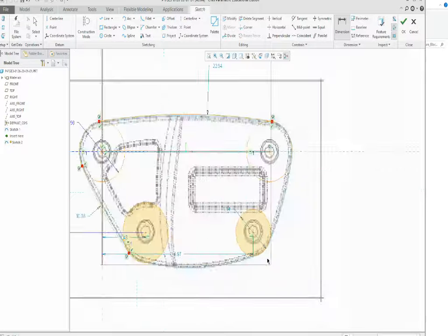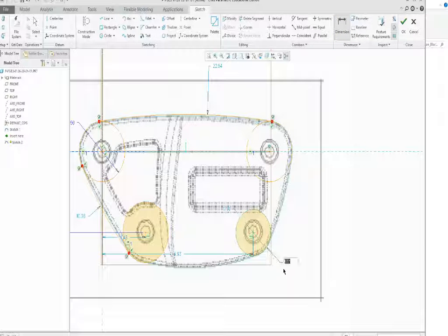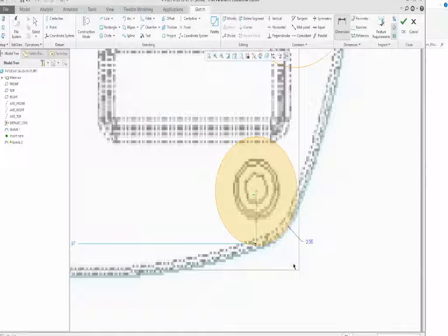So we've got 2 more arcs to do on this design. So we've got another arc that's here. This one's going to be tough because we have a tangency line. We've got a little line here that it's going to want to snap to. So first thing I'm going to do is probably come in and throw a dimension here. Pop it. And that can be a 0.5 or a 0.6. It looks like a 0.55 actually for the size, or a little 0.6.